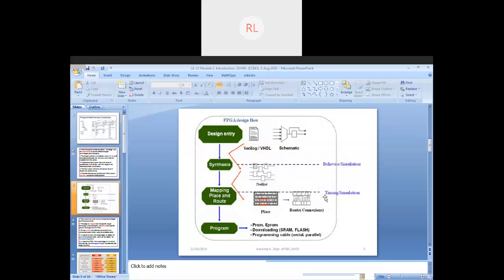and the connecting wires running between them will increase your capacitance and your resistance, and indirectly it is going to affect the performance, right? So how do I say the performance is affected? It's because the data is not being delivered at a particular set of time. So ultimately this step, your placement and routing, plays a very important role.